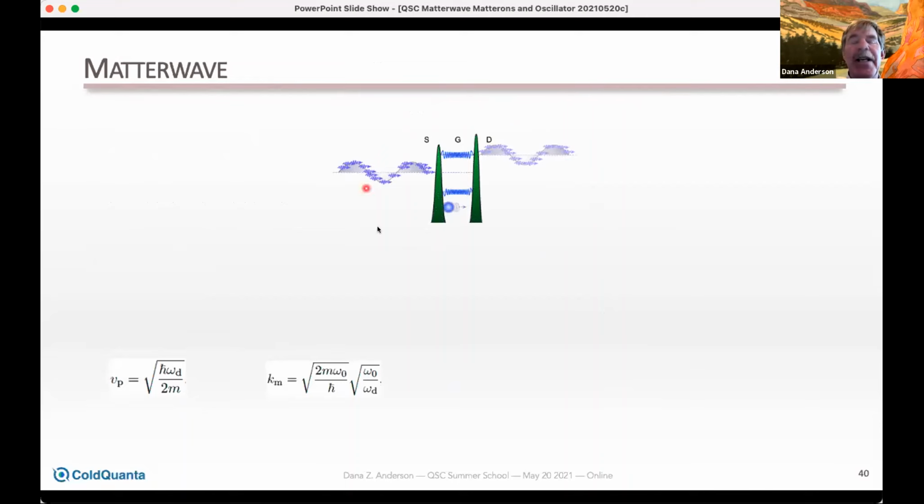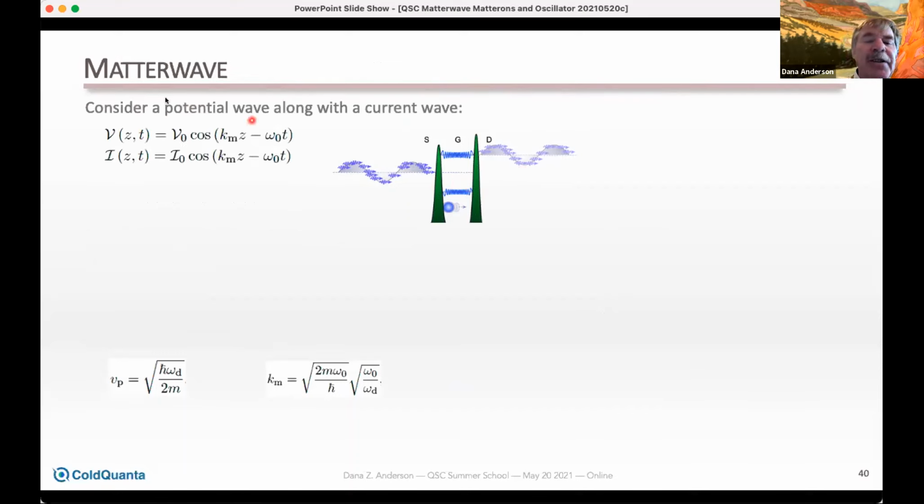So let me start pretending that I never knew about quantum mechanics, but I somehow had this circuit. I would write down this output as a wave in the first place. And this is a classical wave. And suppose I had this classical wave and I said, well, let me quantize it. First of all, before I quantize it, for electrical engineers, this is quite nice because this wave, I'll call it a potential wave, which varies in time, is associated with the current. And potential and current, just like they are in electrical engineering, are related by an impedance. The current is the potential divided by the impedance, and the impedance is just 2 pi h bar. That is, it's just Planck's constant.